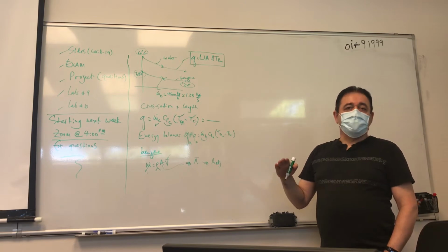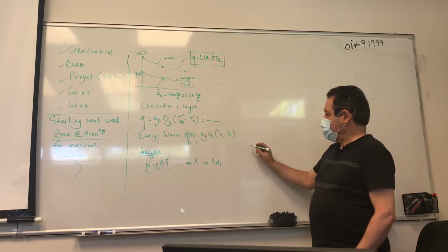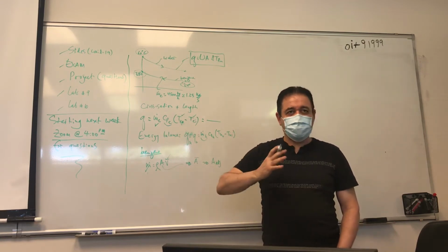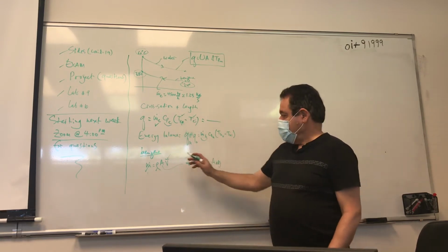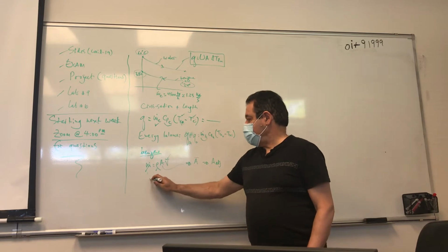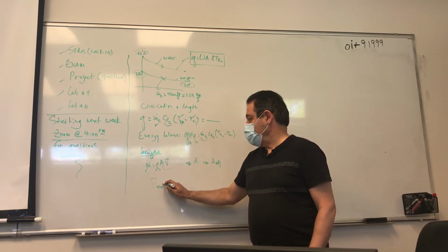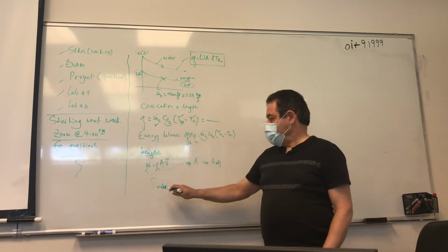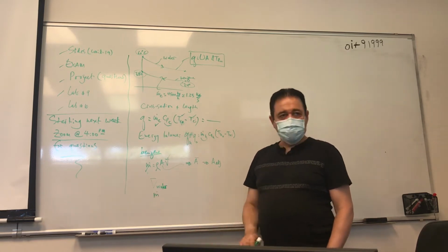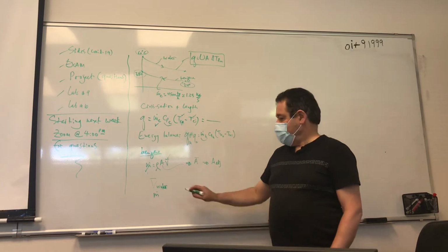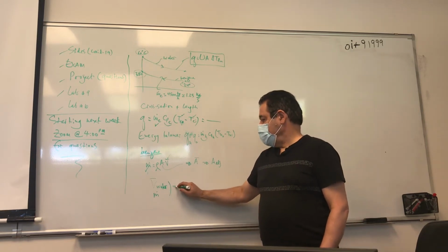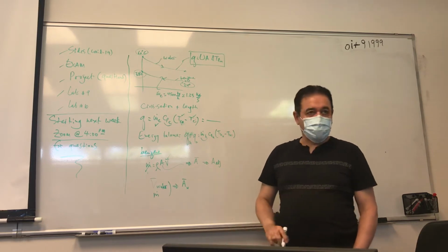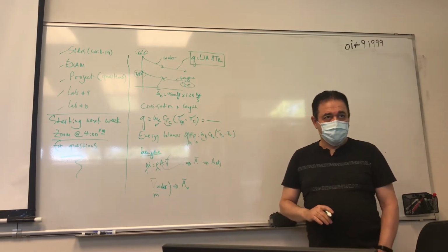And then you may have to choose, because I don't know if you have the benzene flowing inside or outside, it really doesn't matter, because if you choose an average velocity for the water, and then with the chosen mass flow rate of the water, you can figure out what the area of the water is going to be, right?